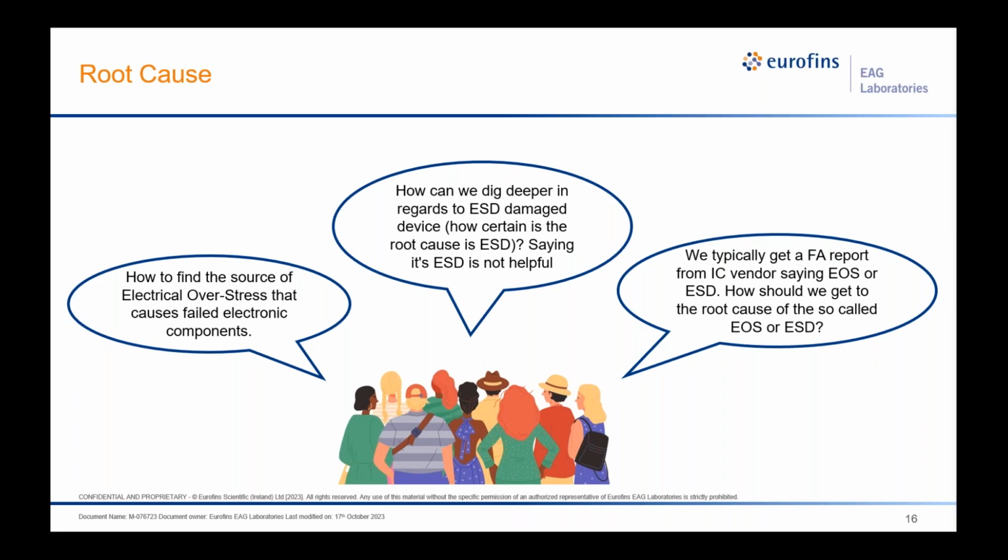testing. We also have a test called transmission line pulsing, which characterizes how ESD diodes and other structures react to ESD pulses or transients in general. So that's actually a good way to characterize some of the ESD related concerns.